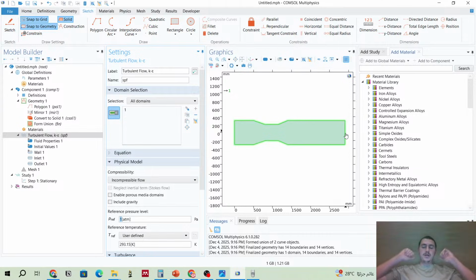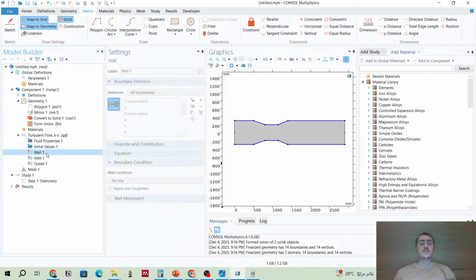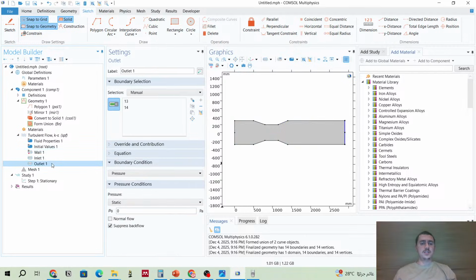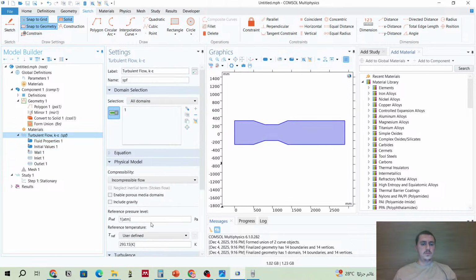The physical problem that we have is something else, but it doesn't matter. For our case, we can just do this for now. Why do I say it doesn't matter? Because it depends on the CFD simulation itself. Is it compressible or incompressible? You can have a compressible flow, but we are working with low velocities. You should calculate the Mach number. But here we know that it's like 7 meters per second. It's very low. So we have incompressible flow, okay?